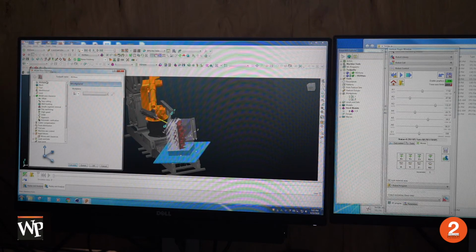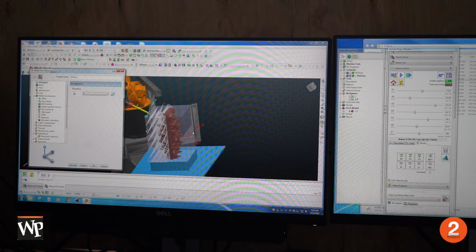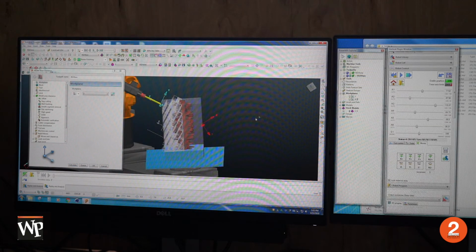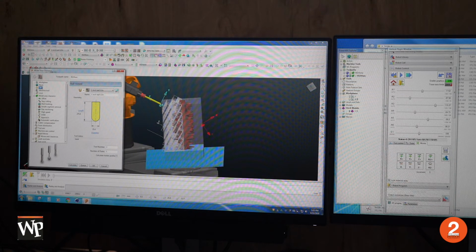So now on my RGH2 work plane, I will choose work plane 2. We can see that the Z will come in at the corresponding angle. That's how it came in from the other side. I'm going to use this. The block stays the same, the tool stays the same, still no limit. This is where we will actually change something.